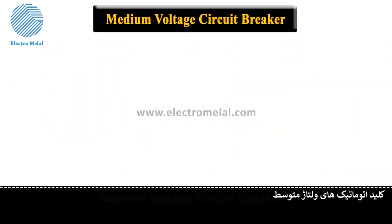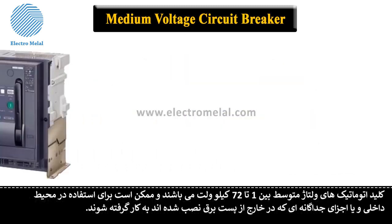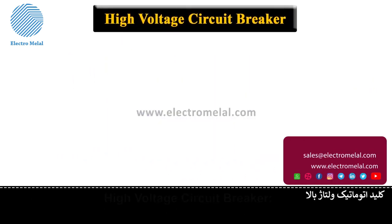Medium voltage circuit breaker. Medium voltage circuit breakers rated between 1 and 72 kV may be assembled into metal enclosed switchgear lineups for indoor use, or may be individual components installed outdoors in a substation. Air circuit breakers replaced oil-filled units for indoor applications, but are now themselves being replaced by vacuum circuit breakers up to about 40.5 kV.